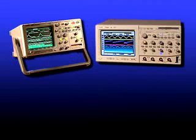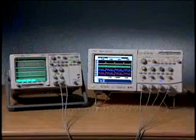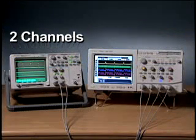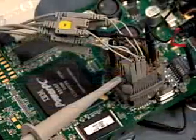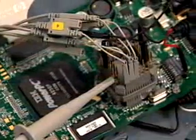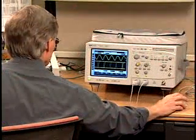Another key selection criteria is how many oscilloscope channels are enough. Consider your most demanding applications as the key determiner of how many channels are enough on a new oscilloscope. Simple debug applications may require only 2 channels, while more complex debug may require 4 channels or more. As digital content dominates more of today's designs, traditional 2- and 4-channel oscilloscopes can no longer guarantee the channel count